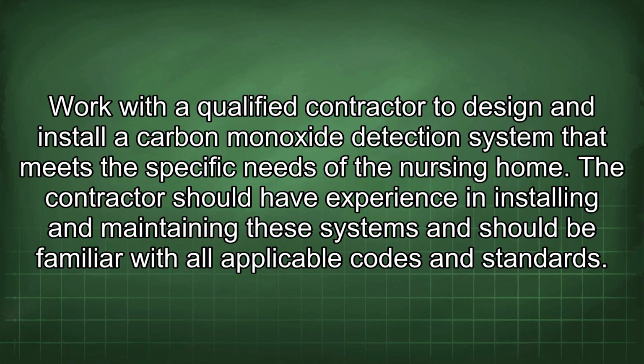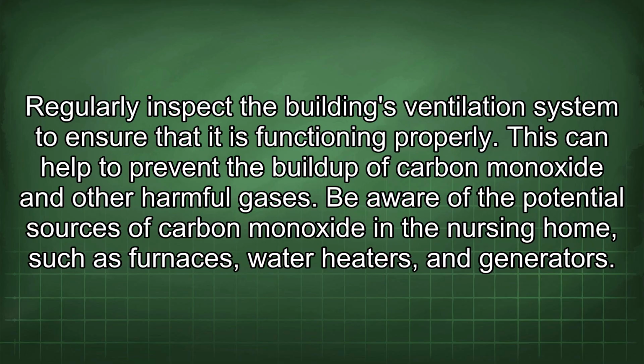Work with a qualified contractor to design and install a carbon monoxide detection system that meets the specific needs of the nursing home. The contractor should have experience in installing and maintaining these systems and should be familiar with all applicable codes and standards. Regularly inspect the building's ventilation system to ensure that it is functioning properly. This can help to prevent the buildup of carbon monoxide and other harmful gases.